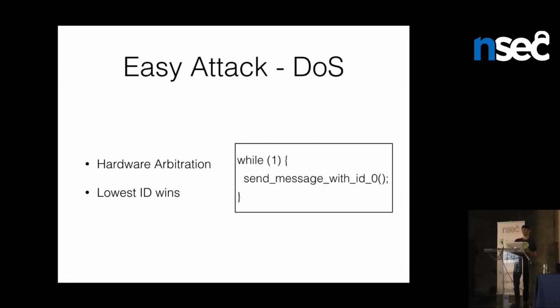Just forever send the ID 0, and in cars this will actually cause some pretty bad things to happen. I've done it by accident once. It set every single fault code on the car, like all the lights just came up, the check engine, service stabilitrak, service. It's not a good idea. I wouldn't recommend it, but it's really the simplest thing you can do. So it's fun to mention.